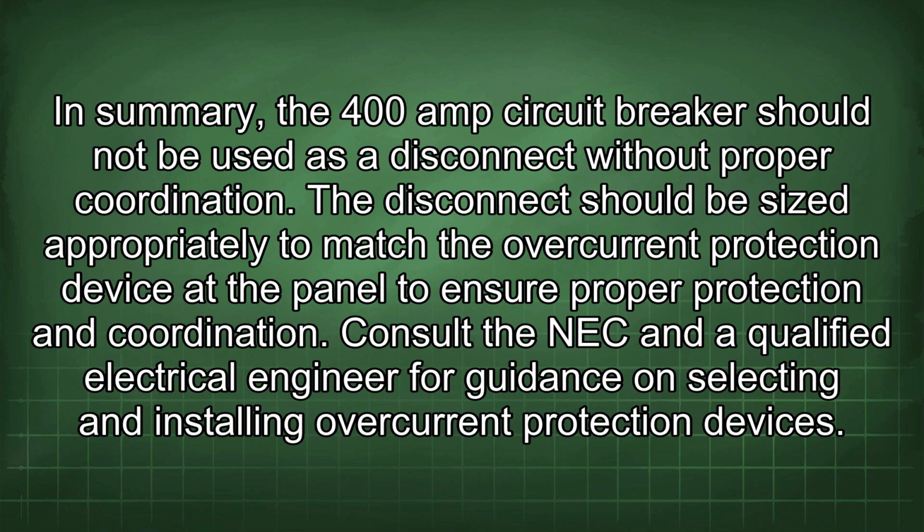In summary, the 400 amp circuit breaker should not be used as a disconnect without proper coordination. The disconnect should be sized appropriately to match the overcurrent protection device at the panel to ensure proper protection and coordination. Consult the NEC and a qualified electrical engineer for guidance on selecting and installing overcurrent protection devices.